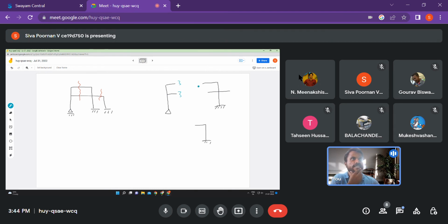Now, I don't need to write this 3 because it's redundant, okay? So, I'll just mark it with black pen. These 3 are same as these 3 due to Newton's third law, right? So, I can have 3 here. And then, there are going to be new 3 unknowns here that have been generated. And those 3 unknowns are known here, right? And apart from this, we also don't know these 2 unknowns. What are the 2? Vertical and horizontal. Here, vertical, horizontal, and moment, right?